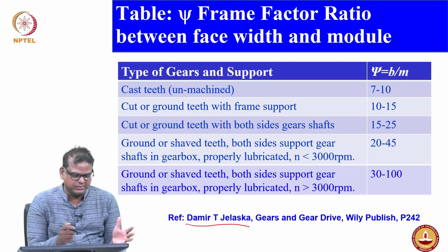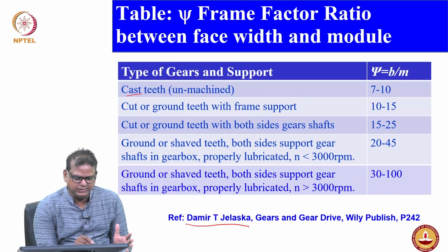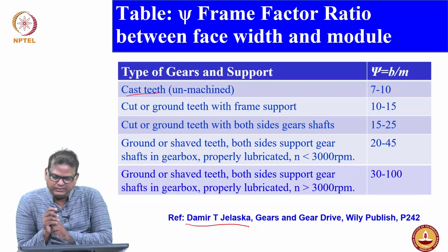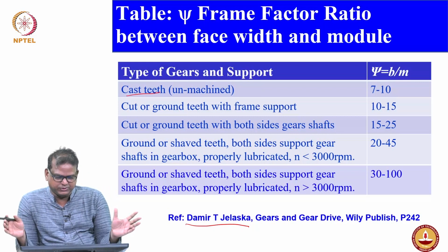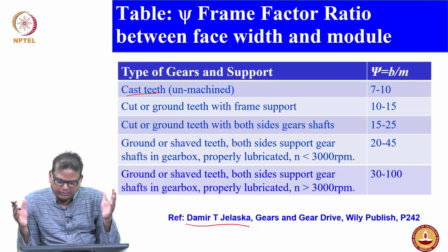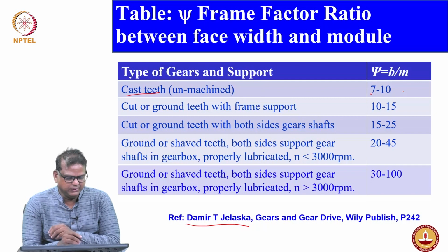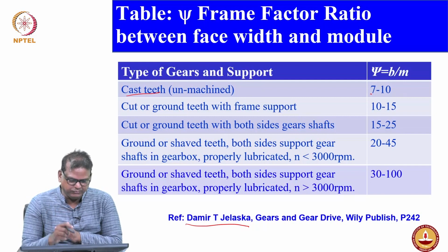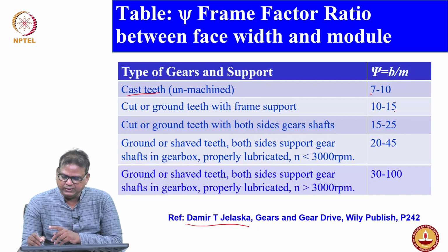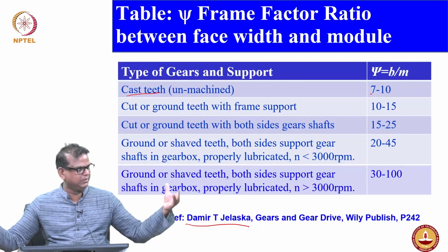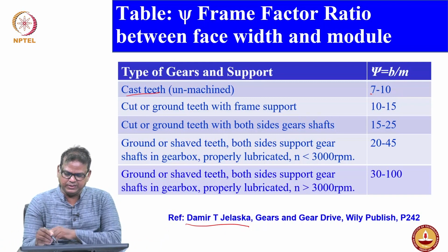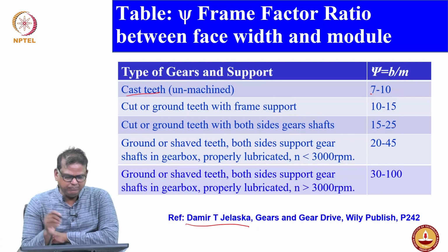If you have only cast teeth without any other support, frame support or bearings, then take the psi value 7 to 10. If you have cut and ground teeth with frame support, 10 to 15. Cut or ground teeth with support on both sides, then 15 to 25.